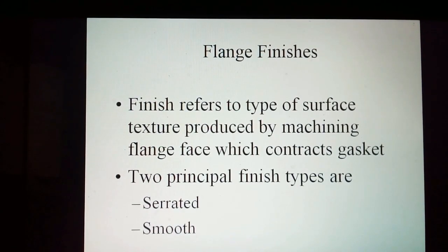Flange finishes. The term finish refers to the type of surface texture produced by machining the flange face which contacts the gasket. Two principal finish types are serrated and smooth.